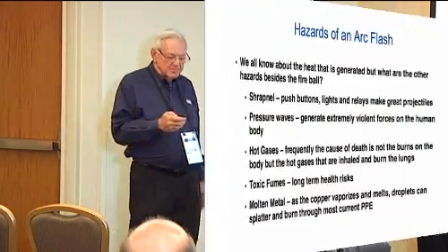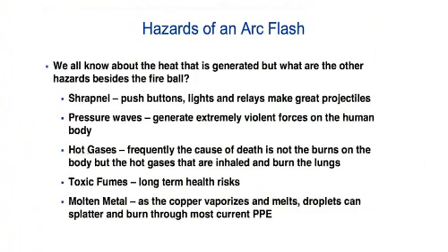All right, so that one aspect of it, as time goes forward, a failure will occur at the stress cone point, or bolts will become loose, then they rattle around. You end up with heat. Heat then decays the copper. When that occurs, then you end up with arcing, and all of a sudden, boom, everything goes up. Okay, what happens when that occurs? Several things. There's shrapnel, there's pressure wave, hot gases, fumes, and molten metal.